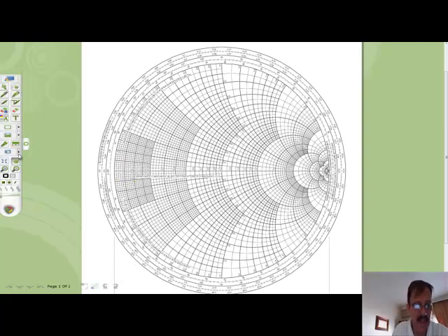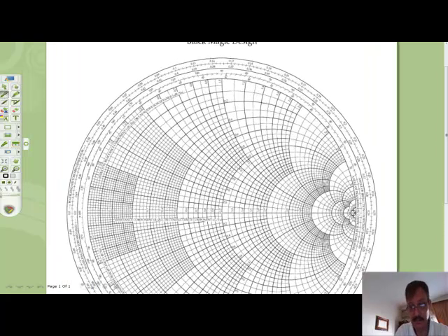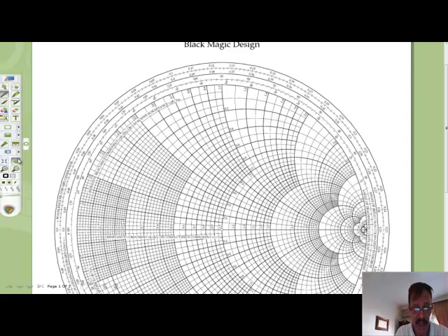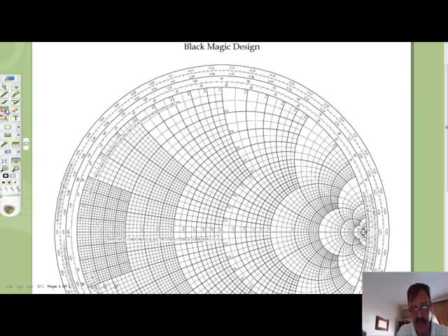Now the ZL that we want to plot is 0.2, and these are the circles that represent constant resistance circles. Here is 0.3, here is 0.4. Now this is the circle that we need. And then the intersection with the reactance circle, which is 0.4.